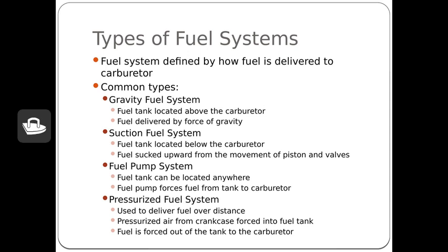A suction fuel system is going to be a little less common in the small applications. This is going to use the movement of the piston and valves to actually utilize the vacuum created by the piston to help pull fuel into the combustion chamber. Another common system is the fuel pump system. This will be on slightly larger applications such as riding mowers and zero turns, where a mechanical pump is going to be used to force fuel from the tank to the carburetor. And then the final system is the pressurized system that's going to use some sort of compression within the tank to force the fuel out of the tank to the carburetor.